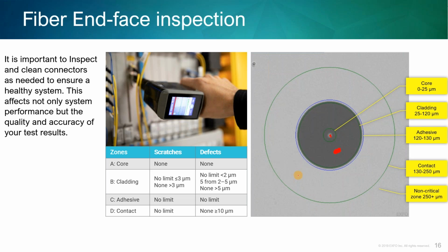But I start cleaning all of my connectors inside of the building, at all the tie cables, at all the handoffs, at all the colo spaces. And I'm not trying to improve my power. I'm trying to improve my reflection. I'm trying to remove something that's causing a larger air gap or some kind of material that's reflective. And so an OTDR can help us troubleshoot which connector within the building to clean. And that's a big part of it, right?